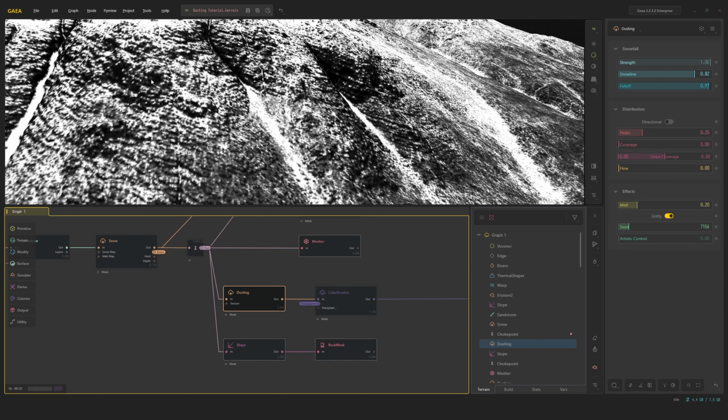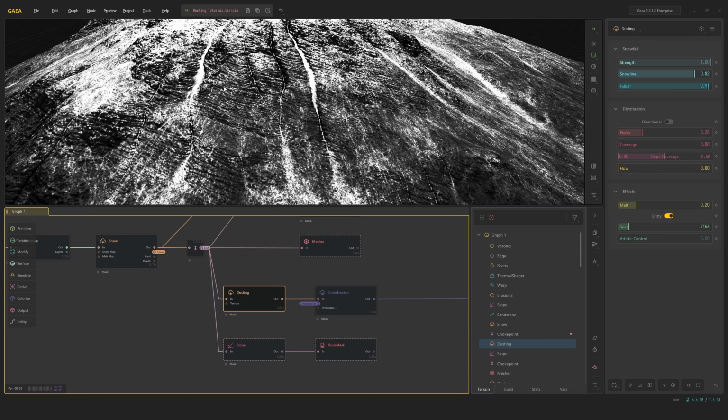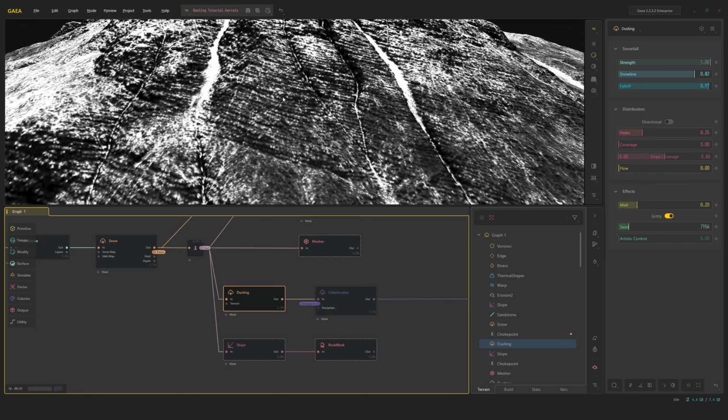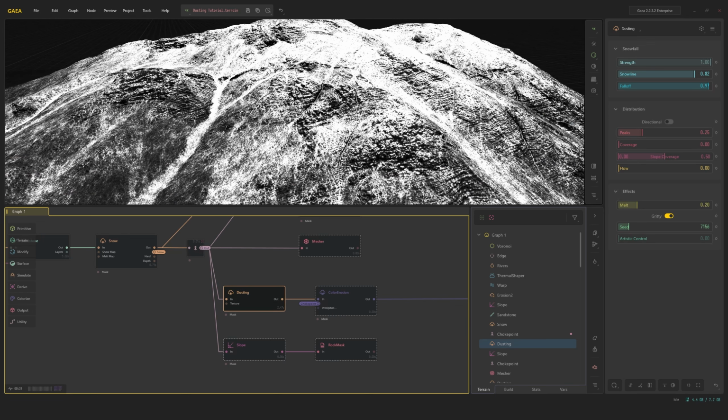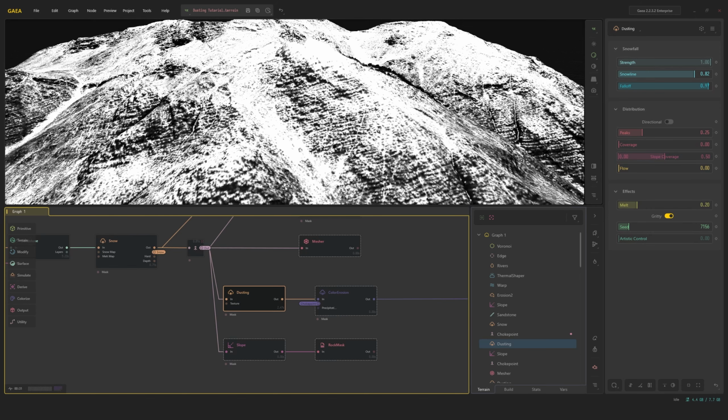And I also opted to keep the flow set to 0 because this way I really maintain that sandstone detail that you can see through the slope here. If I turn the flow up a bit, you'll start losing that detail because it starts flowing over these small ridges. However, because the flow is off, this snow mask is going to be very contrasty and you might actually spot the pixels a little bit too easy if you actually render this out.